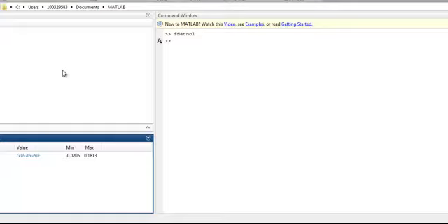All you need to do is use the same name that we used here, which is capital H, or whatever name you used for your filter sequence, and that would be your block in Simulink. So this is the way that we created the sequence for a low pass filter, exported it to a parameter, and then used that parameter in a block in Simulink, which we had for the overlap and save method, or for any other method that you're supposed to implement in this experiment.